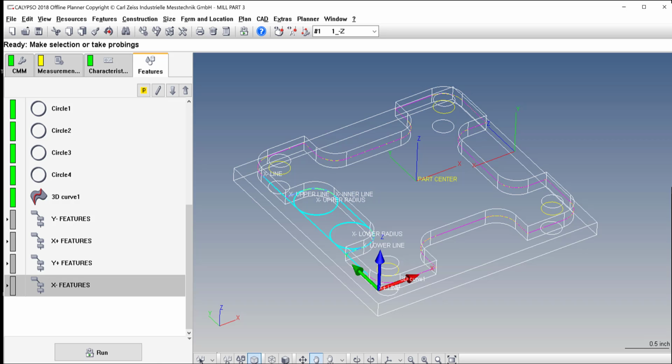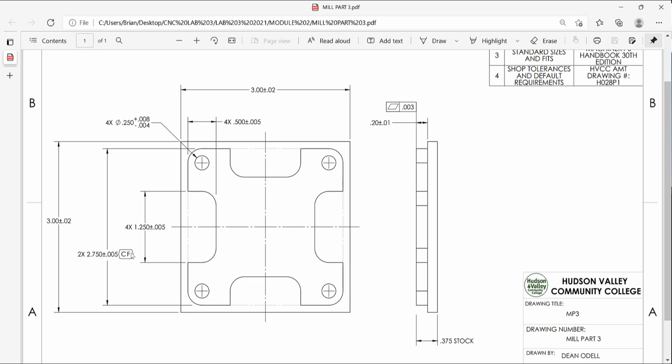If we look at the drawing, we have a dilemma here. To get the 2.75 number in the report, 2.75 does not locate this part on this part, but also this drawing does not tell us: is the outside the datum reference frame and the part to this, or vice versa? What matters to what? There's nothing there, and that's some of the issues with Cartesian coordinates. You don't know what's to what.